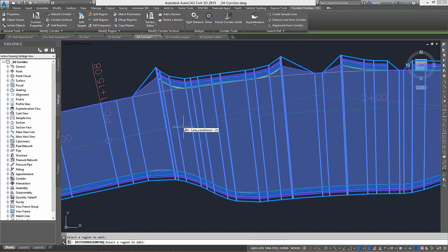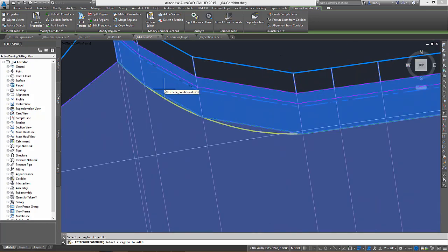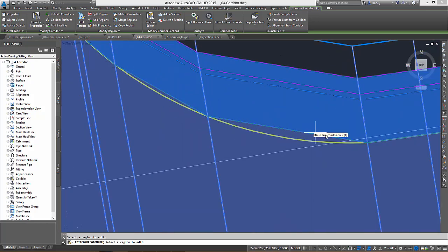All right, it's going to update my model. I'm not going to see a lot of it in the curve that I have here because I'm getting a fair amount of frequency also being added because of my alignment offset, some of the targets that I'm tying to. So we think about that. I've improved my situation perhaps down the center of the road, but I still have other situations outside on the edge. How do I effectively control something like this?